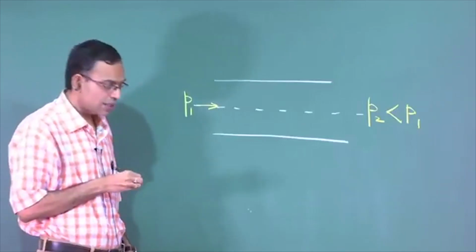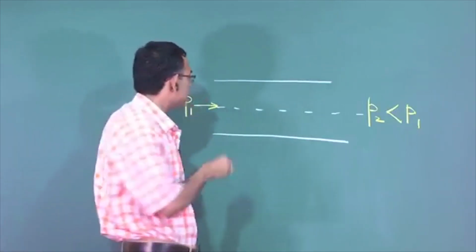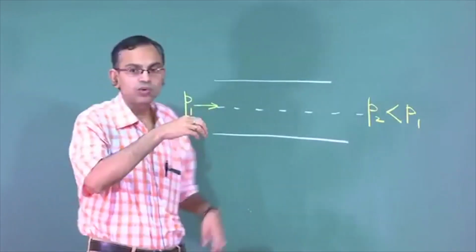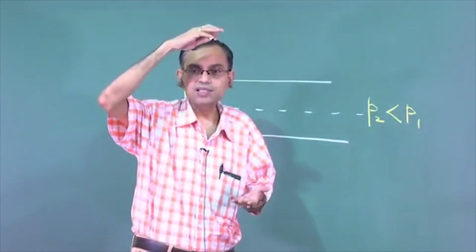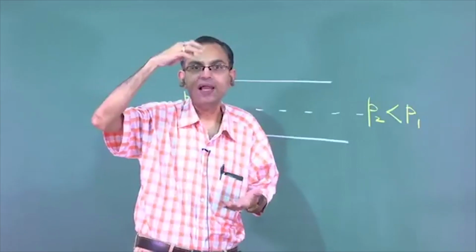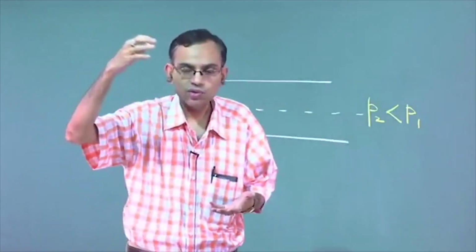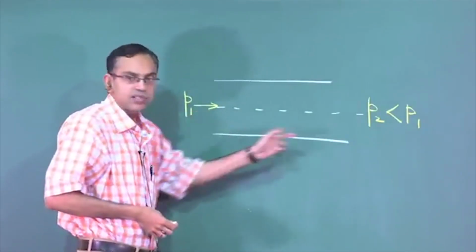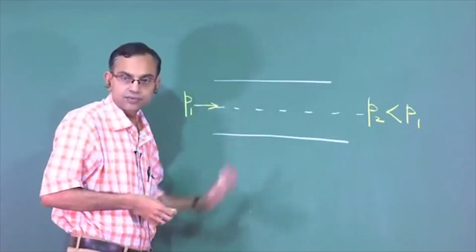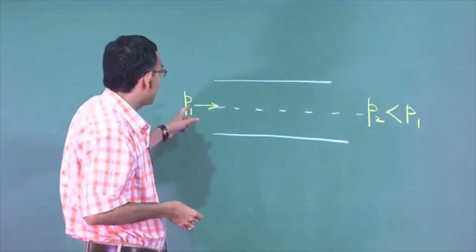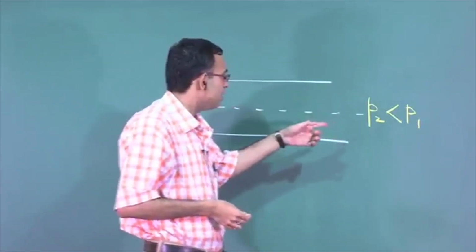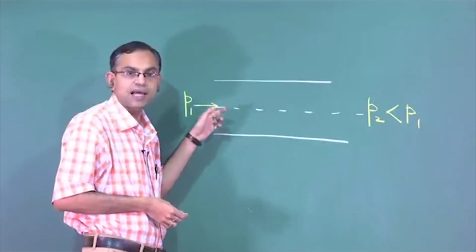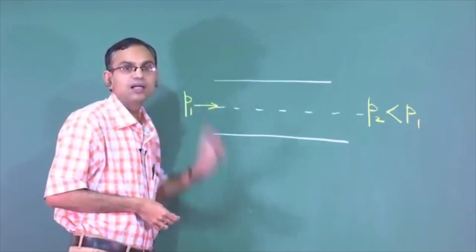Of course, you have to understand that sometimes this pressure includes the fluid pressure plus the effective pressure due to the height, which is the gravity effect, like effective pressure due to height is h rho g. So, that might add to this, but in case of a horizontal channel that effect is nullified. So, what drives the flow is essentially not just P but P plus rho g h, where h is the height, g is acceleration due to gravity and rho is the density.